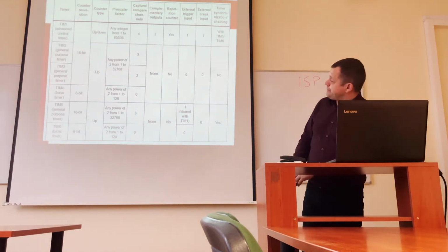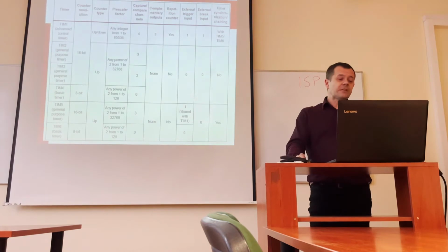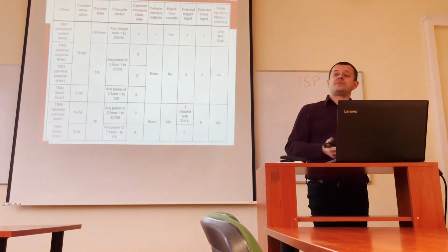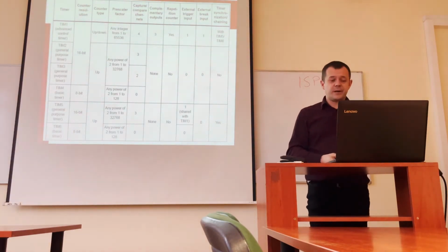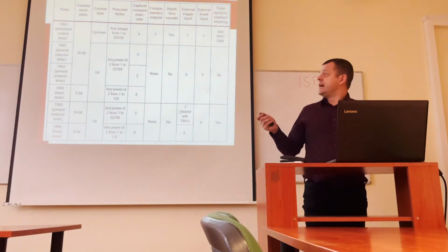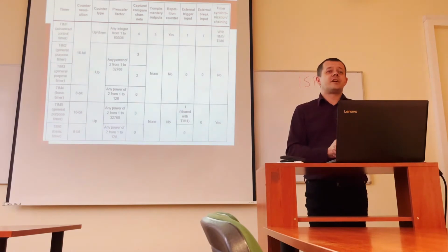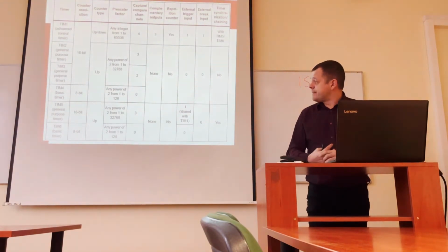What we can see here in this table are 6 timers. One is advanced, three are general purpose, and two are basic timers. We need timers for different functionalities, so there is no need, and the manufacturers deliver it this way, so they don't deliver every timer as an advanced super duper timer. They always decide to reduce the functionality a bit and deliver simpler timers, and that's the case we have here.